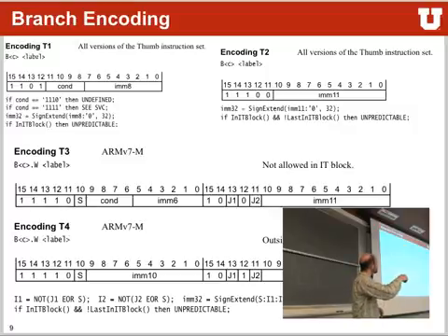Note the difference here again is those have B condition label. These are called B condition.W label. The W stands for wide. It basically tells the assembler that it should use a wide encoding for this particular function. There is also a .n instruction, which means the assembler should try to use a 16-bit encoding for the variable. We will see that later in some real code.